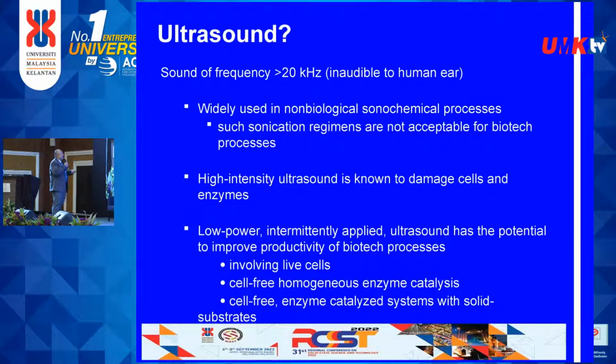At high intensity, ultrasound is known to damage the cell and enzyme. But based on my study, at low power, intermittently applied, 1 second on, 9 seconds off, 1 second on, 9 seconds off, meaning that there is 10% of the sonication application. Ultrasound has the potential to improve the productivity of biotech processes involving the live cell, cell-free homogeneous enzyme catalysis, and cell-free enzyme catalysis system with solid substrates.